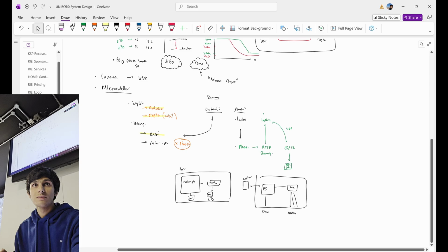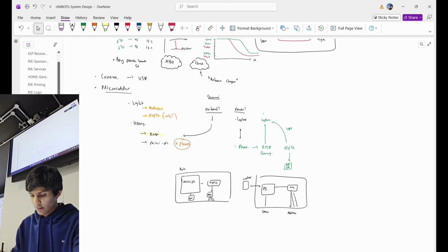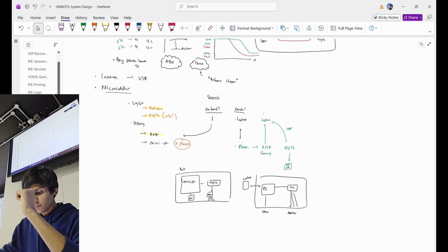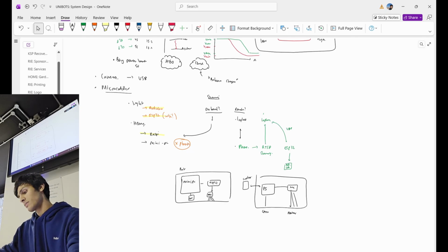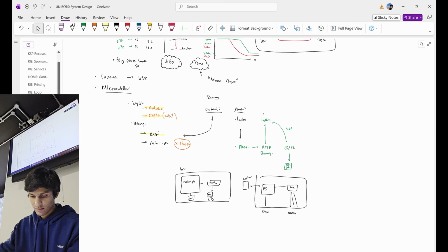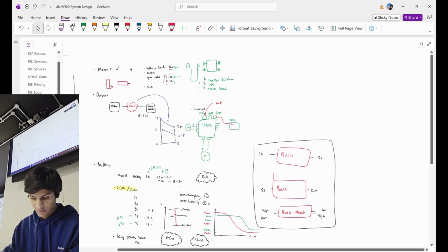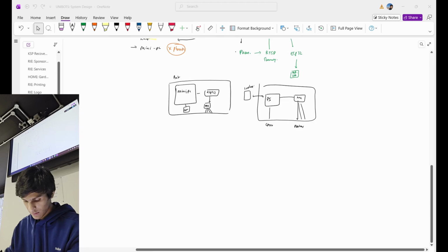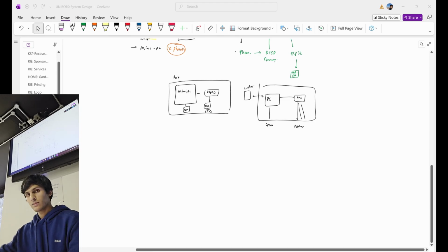It's like vehicles, and your power and your current ranges all the time. Current times voltage equals power, always. Now let's say you have a higher voltage, lower current, you can turn this into a lower voltage, higher current. And it goes vice versa. There is no free lunch, and do pick your wire gauges accordingly as well. Just saying. Okay, I think that's all I wanted to chat about.